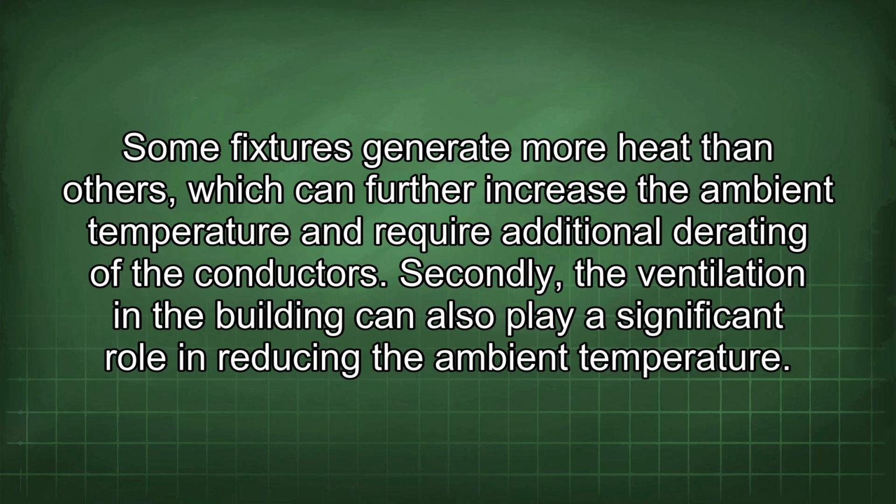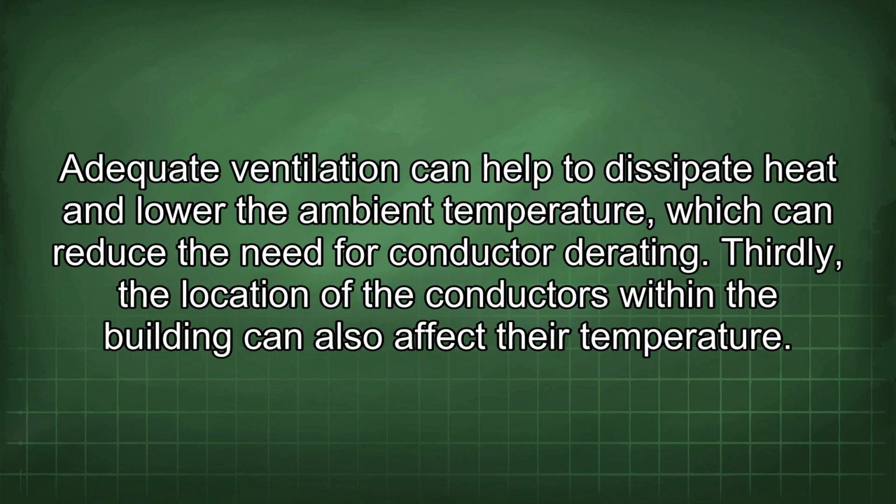Secondly, the ventilation in the building can also play a significant role in reducing the ambient temperature. Adequate ventilation can help to dissipate heat and lower the ambient temperature, which can reduce the need for conductor derating.